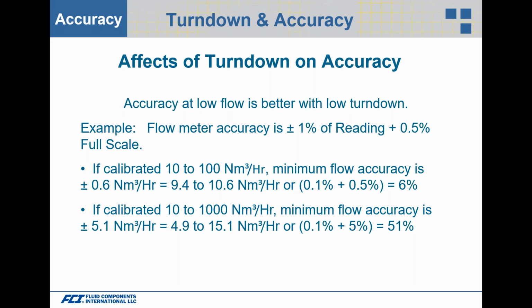To give you an idea though, some manufacturers actually have a statement of the maximum full scale error is 5%, period. So therefore we still use the full scale error up to 5%, and then it stays the same at 5%, even to the minimum flow.